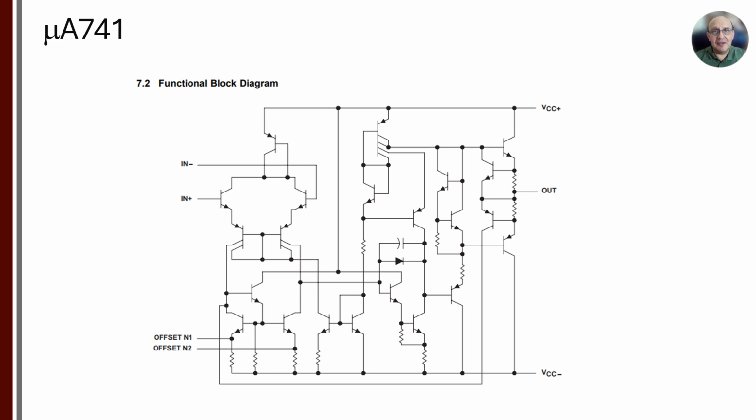Here we have a quick explanation of where these currents come from. We have the two inputs, and therefore we are going to have some current going from left to right. That's our input bias. Chances are transistor 1 doesn't match with transistor 2, and therefore the currents are going to be a little bit different.